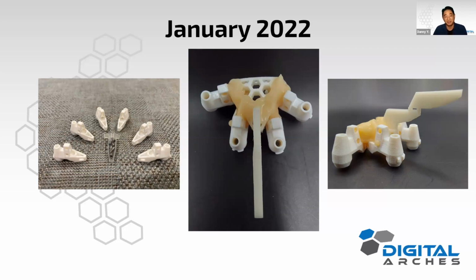And this is actually the point where I made the decision to leave my full-time job and try to get this thing out to launch as soon as possible, thinking that this would be the right iteration. But we did quite a bit of testing with this version of it, and what we found was plastic, and it doesn't matter what kind of plastic we used, whether it was PEEK, printed resin, or some other kind of milled resin or milled plastic material, it just wasn't consistently accurate on every single case. The jig didn't always fit the model.